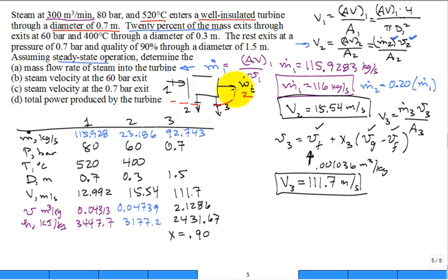We do a control volume analysis. So apply the first law to that control volume around the turbine. And what are we going to pick up for our equation? I encourage you to start with the most general form. Strike the terms that are zero and know why they're zero. But you'll get that W dot out of the turbine is equal to the mass flow rate in at 1, bringing with it its enthalpy h1, and its 1/2 V1 squared.